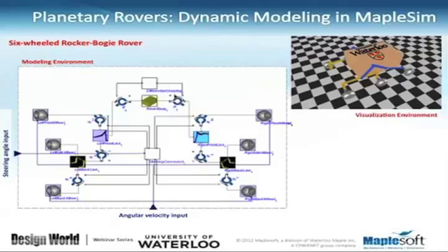Now, the design of this is based on a differential mechanism that sits right inside the body, which means that between these 2 revolute joints there is an algebraic equation, algebraic constraints. And that is done by this block that is shown here on top of the model. Now, if we follow this, then the revolute joint here is connected to an arm, the blue arm that you can see on the picture.